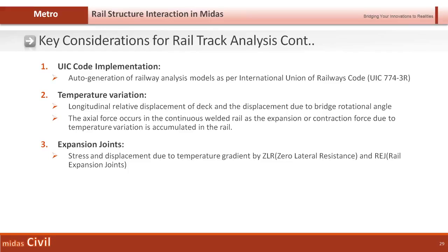Also, due to these high axial stresses, we need to consider some expansion joints at the end of the deck. So to simulate those expansion joints, Midas Civil has a special element called the zero length element. So you can simulate the expansion joint using that.